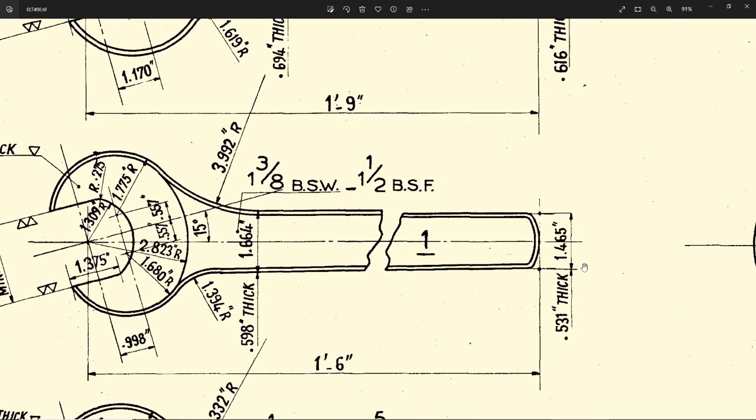This end also has a thickness and a width. There's a radius here that's not defined and radiuses in the corner that are not defined. Well, what I found is working good for me is to use this radius as a value of twice this and then go with a constant corner radius of 1/8 inch in all locations. So there we go.